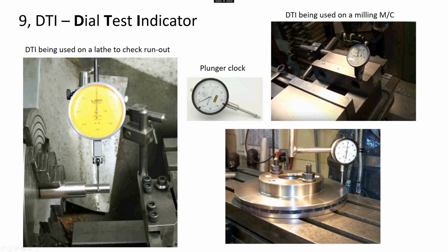One thing to note, when you put the vise on, you should really clock up down the fixed jaw as well to make sure this fixed jaw is true to the machine axis in this direction. Also, if someone's put the vise straight on the machine table, you ought to clock across the bottom of the vise here and here as well. Sometimes you'll put a parallel in here and you'll put the material on top to mill the top. And the reason why you should be checking this fixed jaw is because this one obviously moves and it's not as accurate as the fixed jaw.